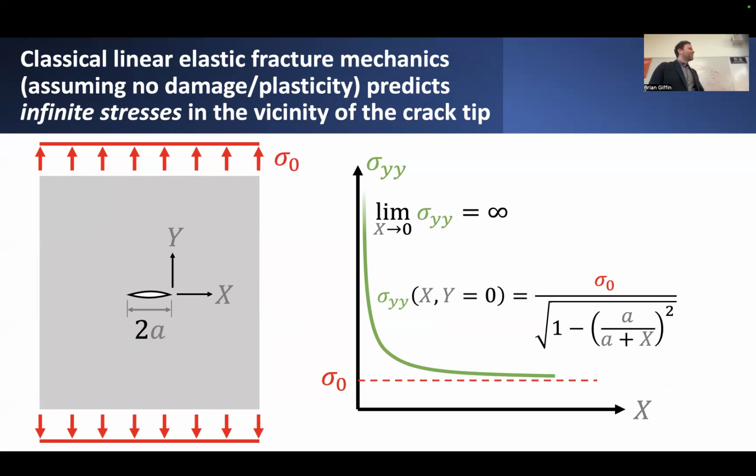All right, so what's funny about this particular problem is that you can in fact come up with an analytical solution using basic methods of the theory of elasticity. But the weird thing about it is, in analog to the problem of the plate with a circular hole, we do expect that the stress distribution across this particular cut plane is going to be non-uniform. In the case of a plate with a circular hole, the maximum stress occurred right at the center of this defined coordinate system, so right at the edge of the hole in that circular plate.